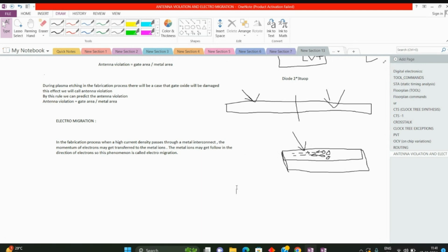Bounds you are applying means you are telling the tool to create some bound over there and keep the cells over there. Maybe because of that your violations are reducing. Even path grouping is the same. You are telling the tool to fix your timing violation. Apart from that, you are not doing anything manual. Even for macro placement and clock balancing, because in the PNR we don't have any authority to change the netlist.